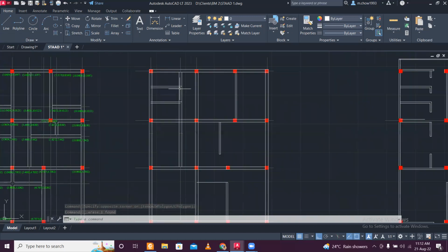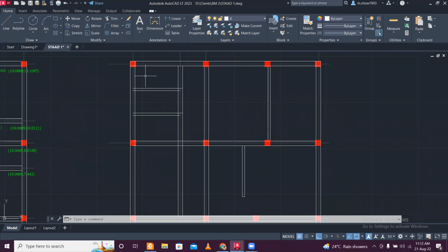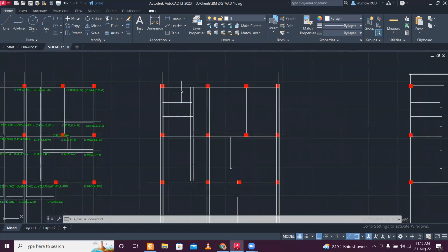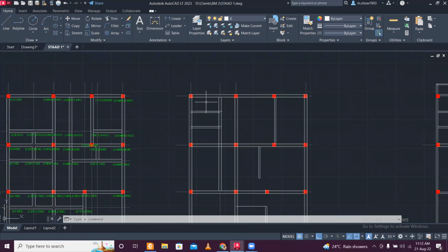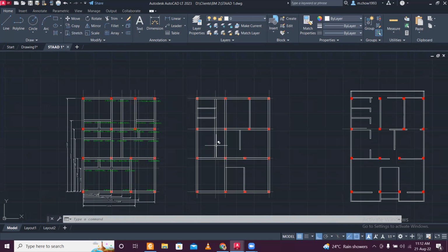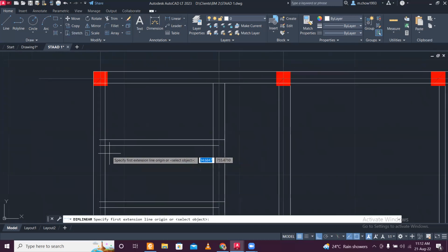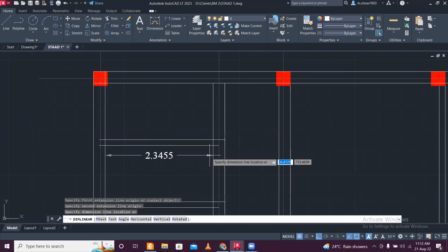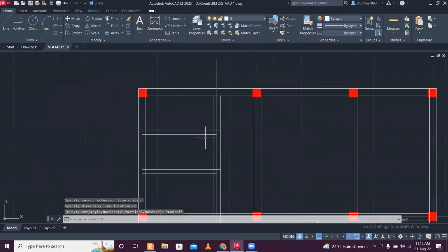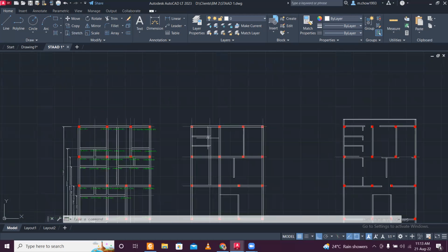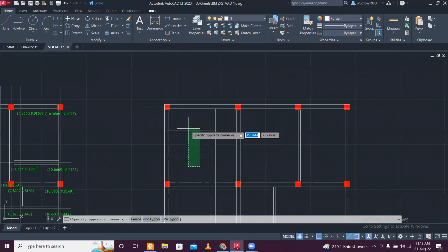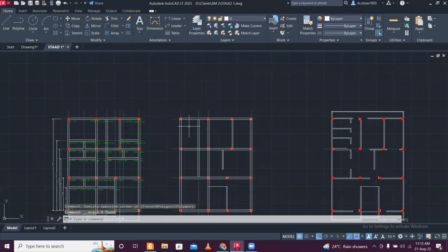So like this, you have created this beam here, and some secondary beams we might also make here. This beam is done here, and look at the secondary beam sizes. If it's less than 3 meters, we ignore it. So it's less than 3 meters here. We'll ignore these beams, and in place of these particular beams, we'll provide concealed beams. So just ignore this. Select and delete this.